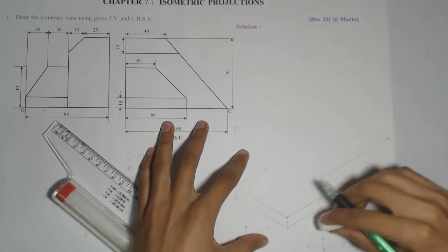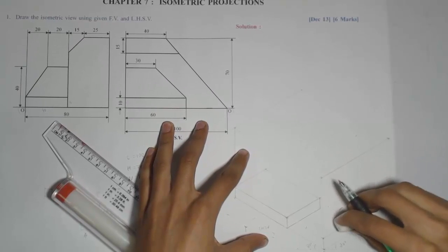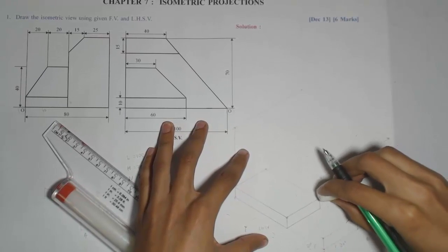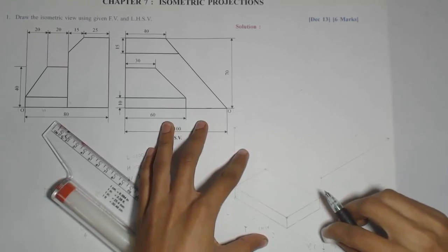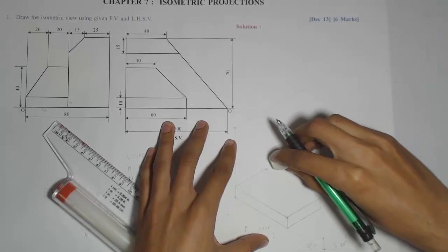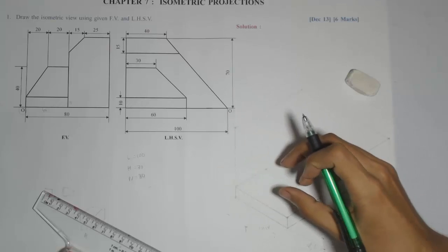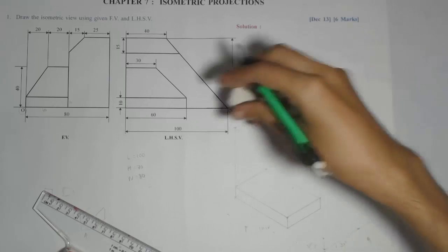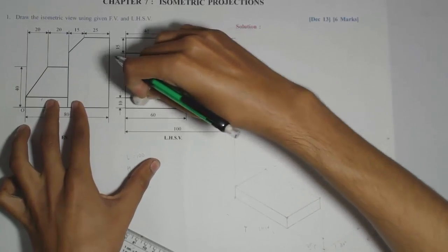Before that, I'll erase the initially drawn parts to avoid the confusion, because if you keep those lines as it is, and if you draw the next part keeping the projectors, then you will be confused because many lines will be there. So after finishing this for one height, now I'll move to the next part of next height. Okay, again we will draw that view on those planes. So first front view on this plane and side view on this plane. So now I'll move, after finishing this part, now I'll move to the next height.